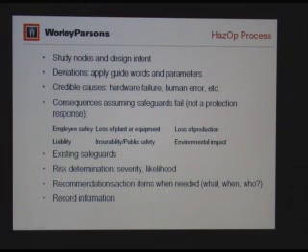So the consequences need to be considered in different ways, like employee safety, loss of plant or equipment, loss of production, the liability issues, the insurability and the public safety, and we also have to consider the environmental impact. And then we have to examine and find out what the existing safeguards are that are already in the process design.